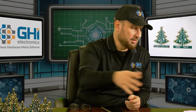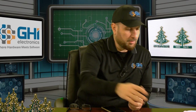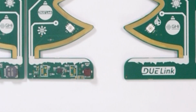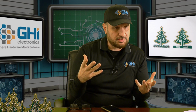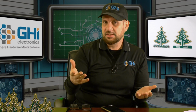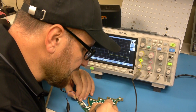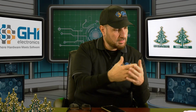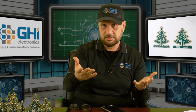The symptom was that on a lot of these trees, the LEDs would not come on. The processor, the micro right here, would work fine. It connects to the PC, we can load software on it, everything works as expected, but then the LEDs would not come on. Check the voltage on the LEDs, voltage is there. Check the signal, grab a scope. Scope the signals. These are smart LEDs, so they're controlled over digital wires, over an SPI bus or SPI-like bus.